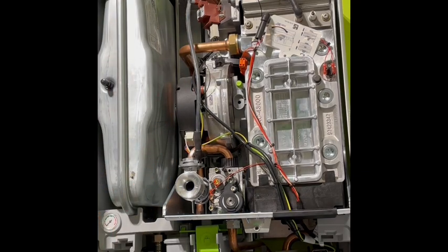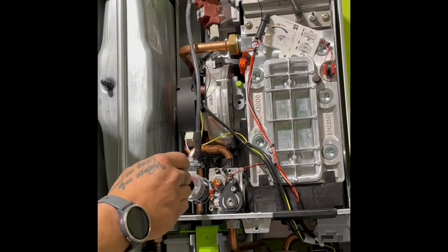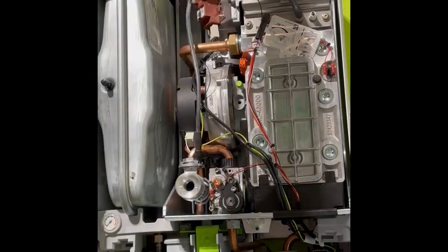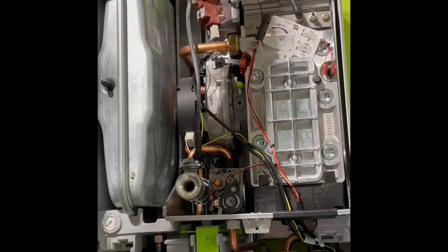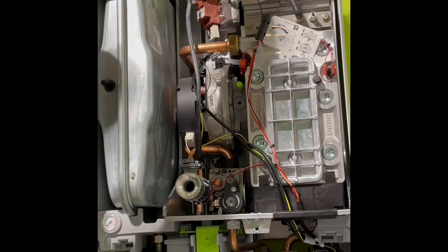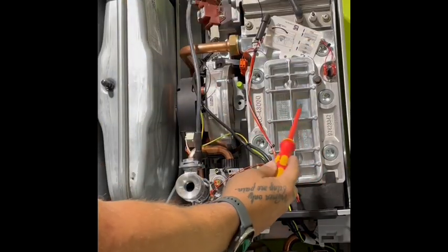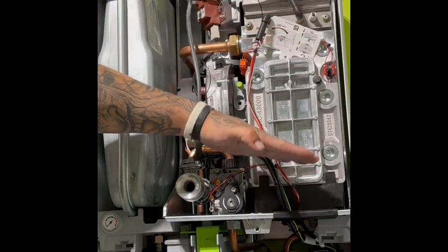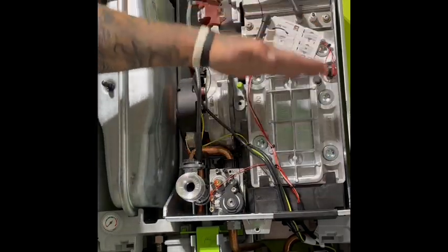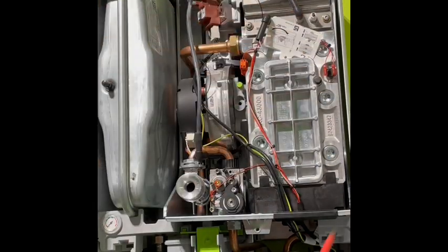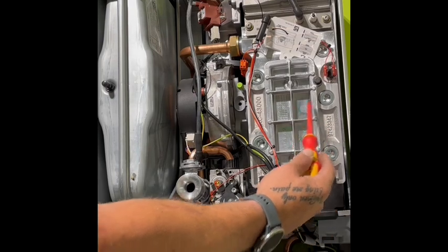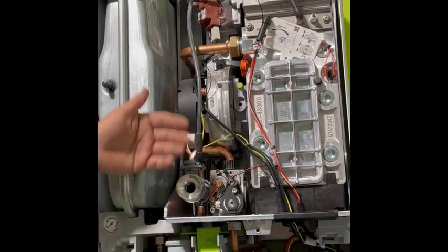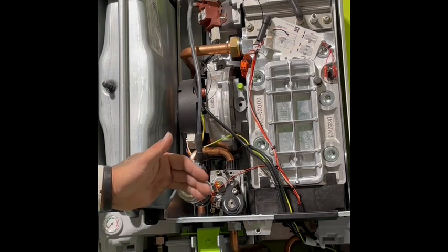So what we're going to be looking at is, are there any blockages in the venturi, air intake at all? Is there anything in there? Is the burner okay? Is there any damage to the burner? Are there any blockages in the burner anywhere? Is the heat exchanger mucked up? When this boiler is manufactured and designed, it's designed so it's got enough volume of air inside there for combustion. If that starts blocking up, you're just restricting the air inside the heat exchanger. If you're restricting the air, you're going to get incorrect mixture of combustion.